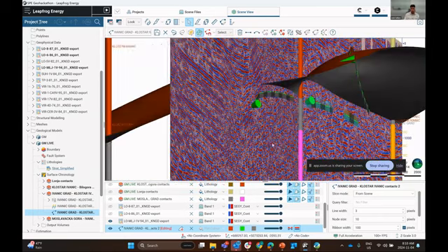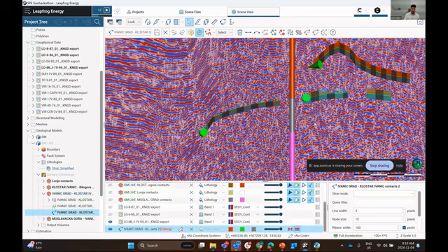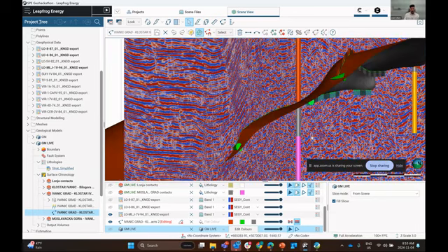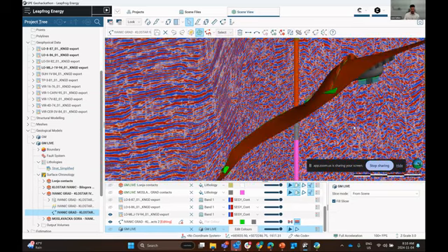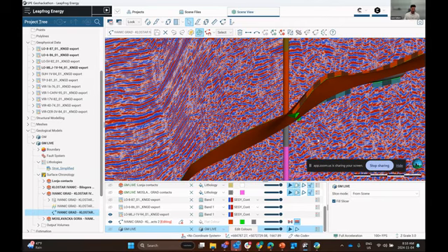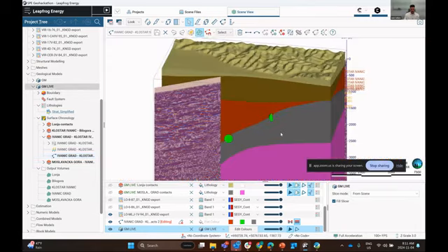So we've adjusted this surface with these 2 new polylines that are drawn on this particular object, and if we press save, you can see here that the structure of this surface conforms to the polyline associated with the drawing on this 2D seismic section and this drilling contact. So it informs the surface, which then informs the volumes.